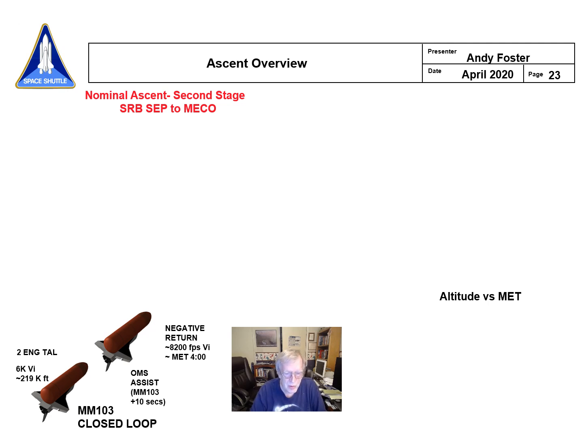It was a 2 OMS engine burn, and the time on it varied. It wouldn't be any longer than about 2 minutes. The other call you would hear shortly after this was negative return, and that is telling you you can't go back to the Cape anymore if you would need to do an RTLS for some reason. And again, we'll talk about those in the RTLS briefing.